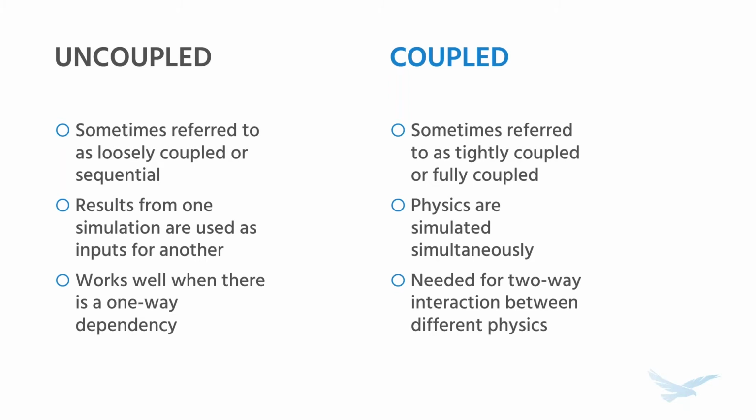I agree, Terrence. I think that's the best way to describe it as a sequential thing. It's solving the pressure distribution on the billboard and then solving the displacement. If you've ever watched a billboard dance in the wind, that's maybe something called aeroelastic flutter. And that's a dynamic problem where the pressure on the billboard causes deflection, which then changes the pressure distribution and changes the deflection. There you would need that coupled, and maybe that sequential isn't the right approach for the flutter kind of thing. Does that make sense to you, Terrence? Yeah, that's absolutely right, and exactly where I was going with this slide. So that's perfect, Tim. That's a great example.